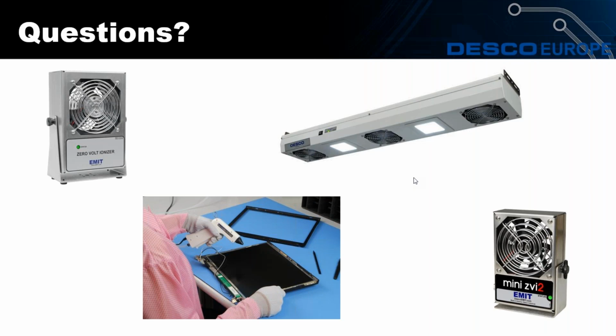Last question in this section: how often should you test ionizers? Vaughan's gone through some of the test equipment already. I'm coming up to the test equipment, we'll be coming to that. But in terms of the frequency of testing, we say that our ionizers should be validated once per year as a minimum. But really, you have to determine for yourself the test frequency that you're going to put in place.